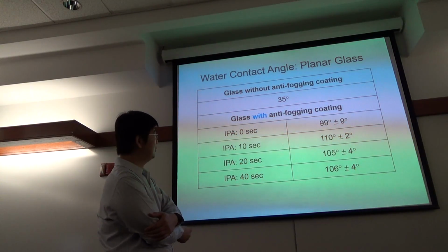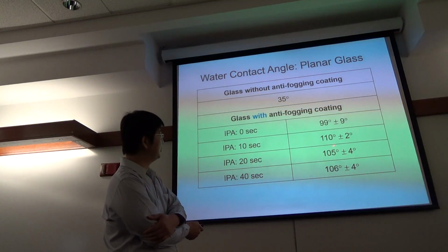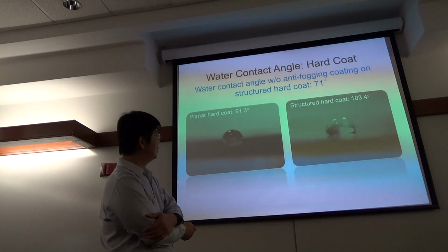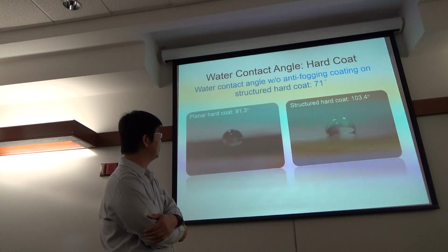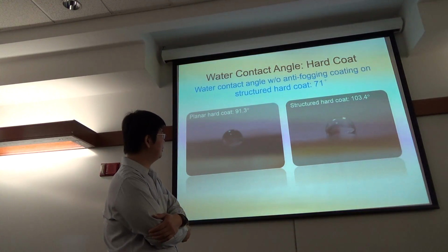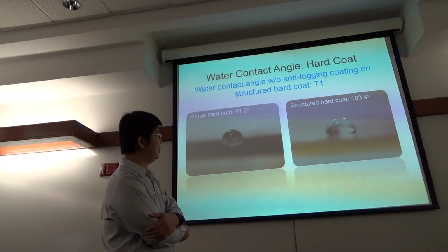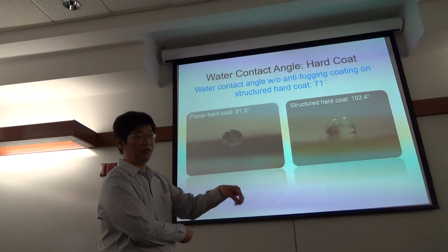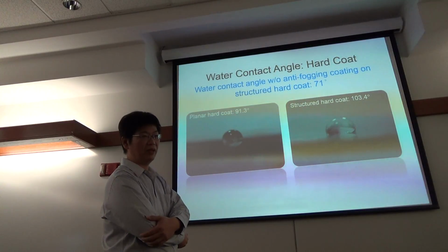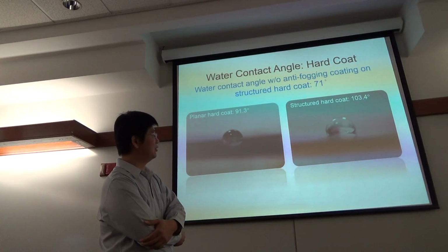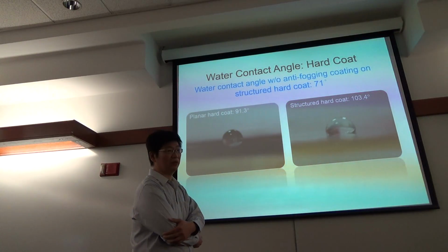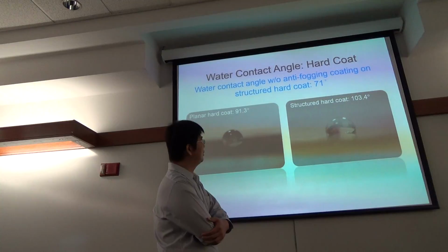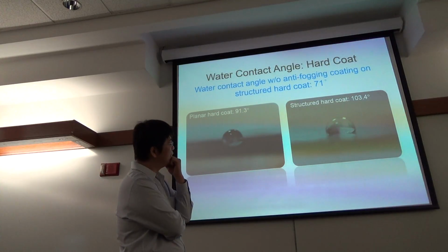So the water contact angle is pretty good, but for oil, maybe not so good, but acceptable. And because the hard coating layer is pretty strong, we can use the HF dip and there's no harm. So I'd say they can resist typical chemicals. That will be no problem. Okay, good. And what else?